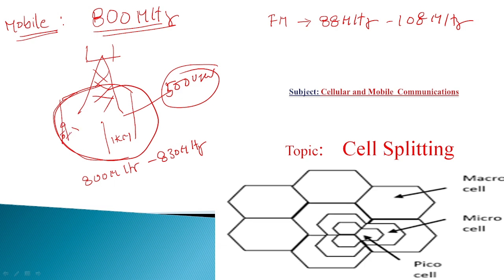This is the transmitter, and here at this end is the receiver. While two users communicate between two cell sites, because of the long cell coverage area the signal strength may decrease because of valleys and hills. Also I need to increase the number of users. That's the reason the original cell is split.